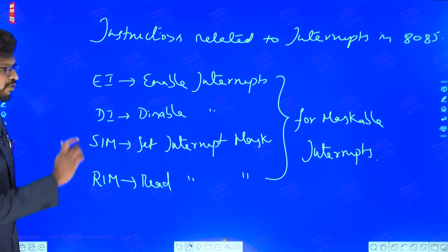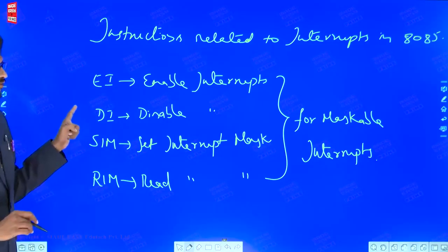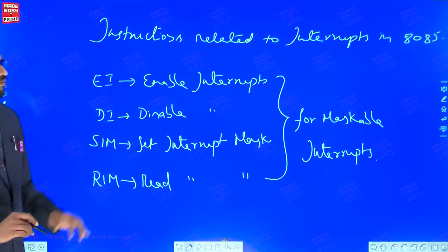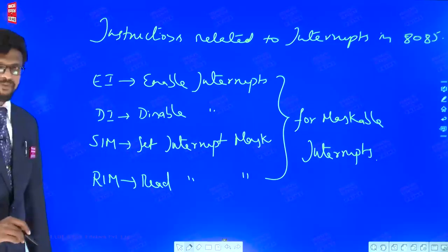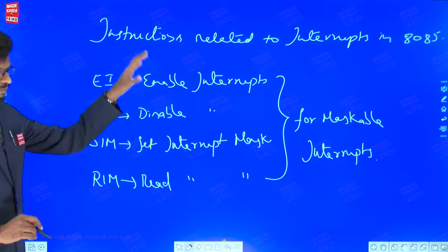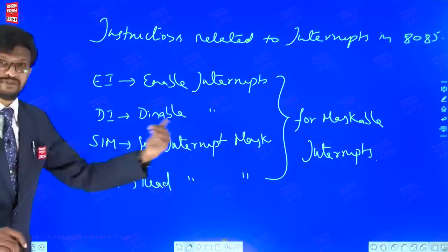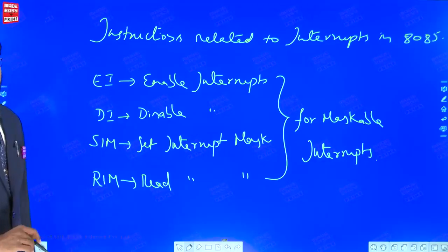So never forget the flow which I told you. When an interrupt is received, the processor will first store the next value, meaning the PC value, into the stack memory. Hence, it will go to the ISR program, the application program, run it, come back to the main program by picking up the PC value from the stack, then it continues the main program. So that is how the sequence can be understood.